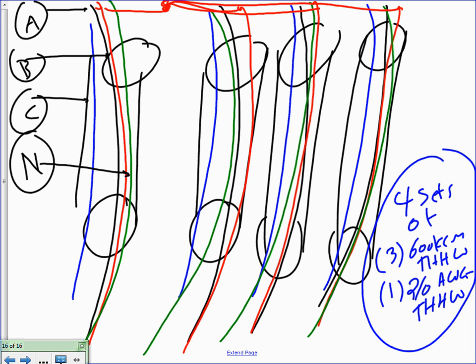They tie them together, and the same thing, only one phase to give you the gravity. They all tie together, right? Not this way. They all tie to one location. Can you guys see that? At both ends, can you guys see how they're tied together? I'm showing only one. They have to tie to the same set of lugs on both ends. That's what paralleling means.